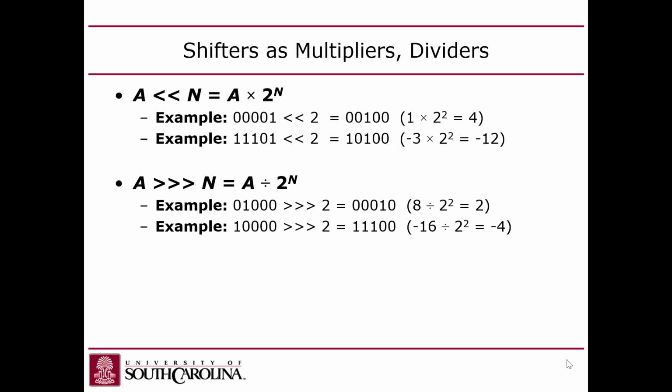Okay, now if I shift this to the right by 1 bit, in this case, I'll do a logical shift, because I'll assume this is an unsigned number. So I'll shift in a 0, and I'll get a 1, 1, 0, right? Which is a 6.